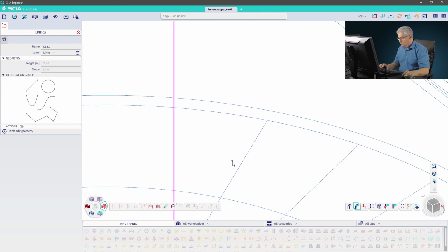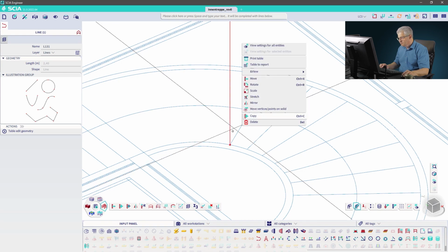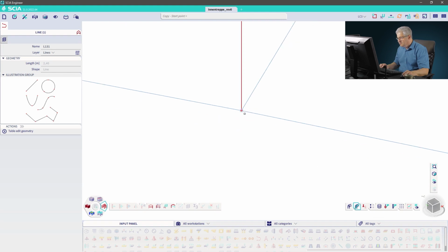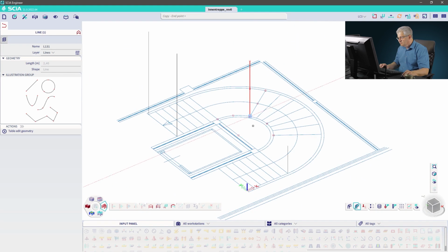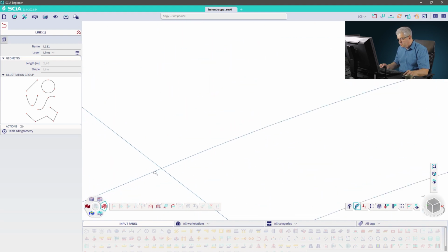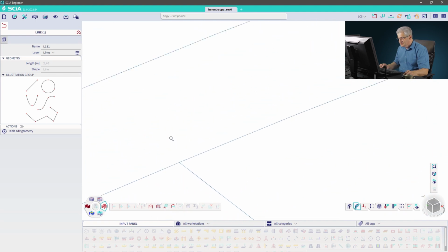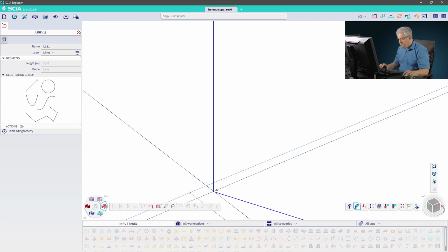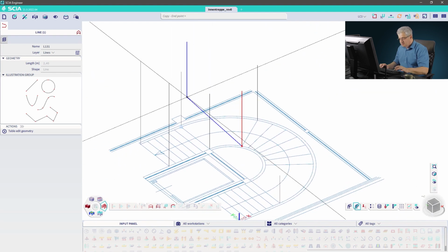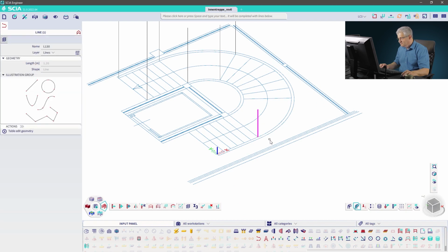So this is finished. Now I will copy this one, but I have to zoom correctly. Right mouse button, copy, start point. Start point is here. It's correct. Okay, this one. I have to zoom very deep because I'm not sure if the lines are connected. This is sometimes a problem if you get drawings from outside of your company. You know that sometimes you have more work with correcting this drawing than with the drawing itself.